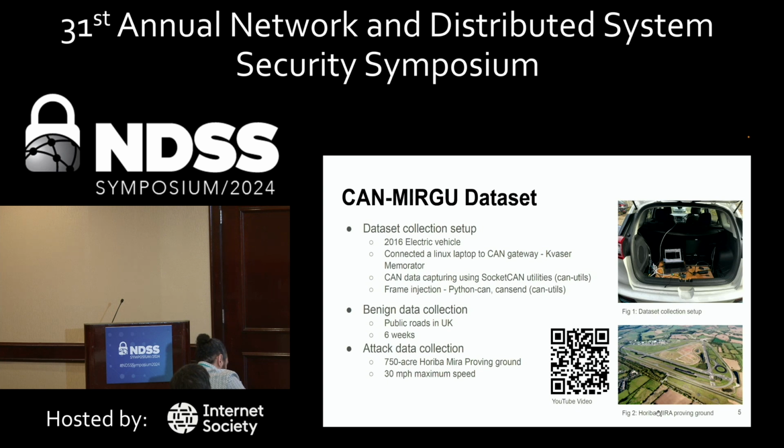We connected a Linux laptop to the CAN gateway through a Kvaser Memorator and used SocketCAN utilities for the data collection. For the attack frame injection, we used a Python script created using the Python CAN library and the cansend command in the CAN utils library. We collected 17 hours of benign data over 6 weeks. During this time, the vehicle operated on public roads in the UK, engaging in a wide variety of normal driving activities.